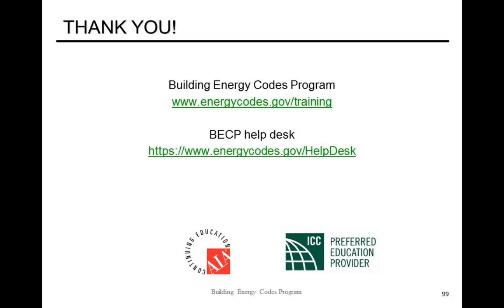The standard practice that I referred to is in the actual rule set of the manual. So the baseline building description is the standard practice that I'm referring to. For instance, the baseline building, we talked about this, for a large office building over 150,000 square feet, has 40% window, and it has a VAV system with a water-cooled chiller and a boiler. So that's the standard practice. It is described in Appendix G itself.